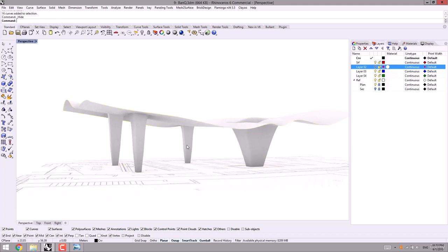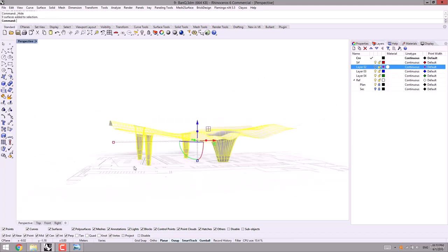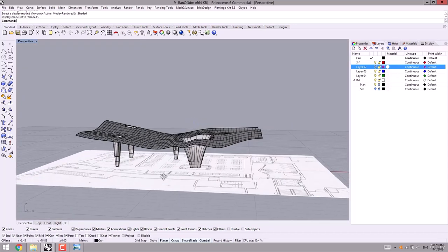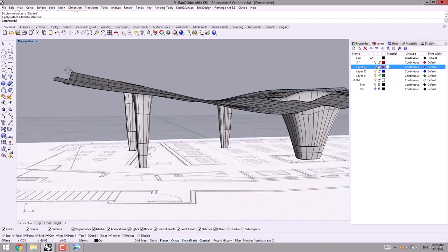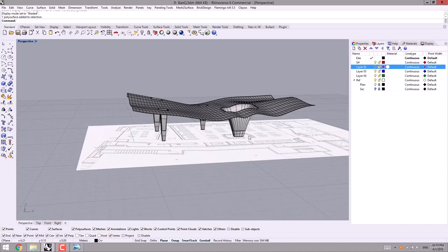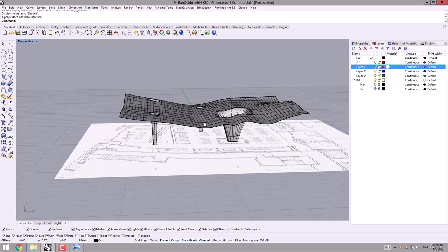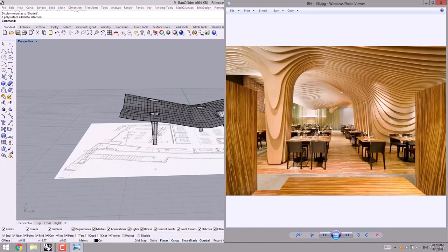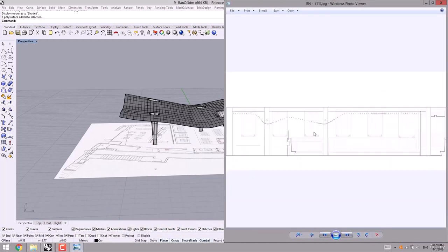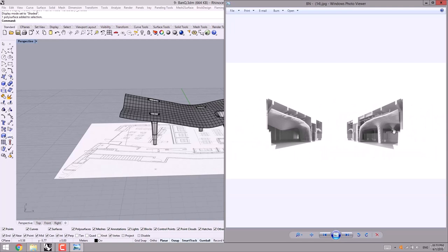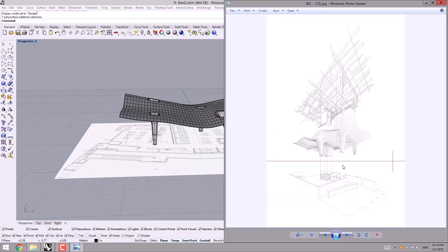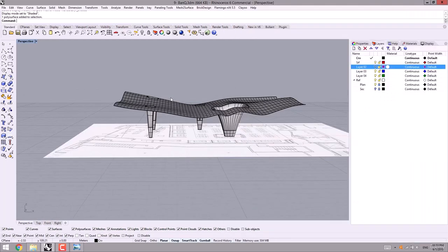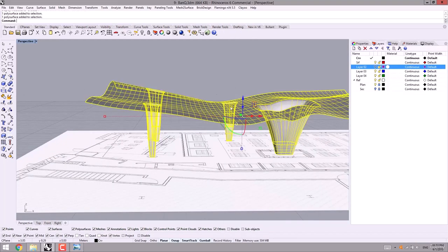We have created the columns and also the surface. I use Sel Curve to select the curves and hide them. Then I join the surfaces with each other. Check it out. Then in the continuation, we should cap the top face or fill the openings, and we also have something to do with the base part because we're going to use the contour command for creating such a roof. We want to create these layers and then extrude them.